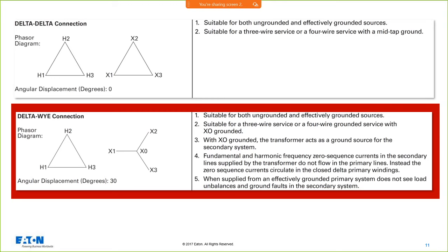There were benefits for a delta delta in that it was very stable. That first ground fault's a gimme, but that second one's a doozy. But you would lose a lot of motors and things of that nature due to transient overvoltages in those delta ungrounded systems. That's why they corner grounded those delta systems.